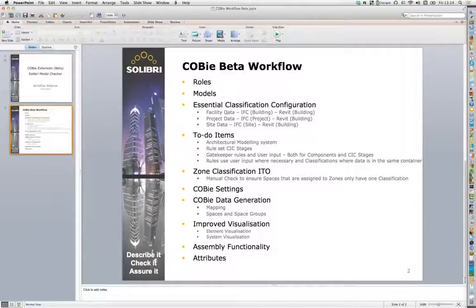So when we're looking at facility data, such as the building name and the building description, that should be based at the building level in the IFC tree. And Revit gives it in that location, and so does ArchiCAD, and any COBie compliant data should put it at the building level. But Revit also creates its own fields to actually store this information. So rather than just putting it in the building name, they'll put it into data facility name, and that means obviously you've got to map those different locations.